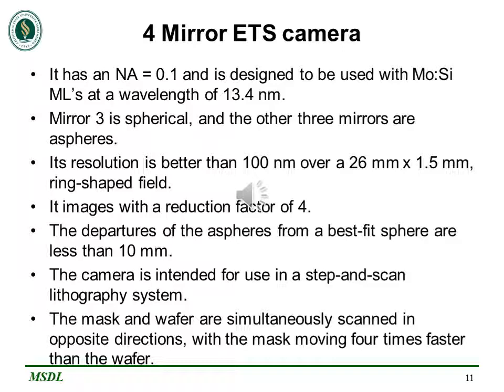These cameras are for use in the step and scan lithography system. In actual operation, the mask and the wafer are simultaneously scanned in opposite directions, with the mask moving 4 times faster than the wafer.